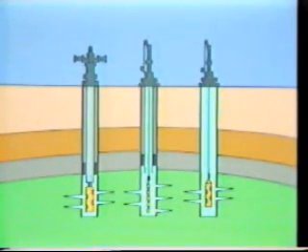Underbalanced perforating is a technique which relies on the sudden force of the flowing hydrocarbons to flush debris from the perforations and ensure that none remain plugged, causing lower productivity.